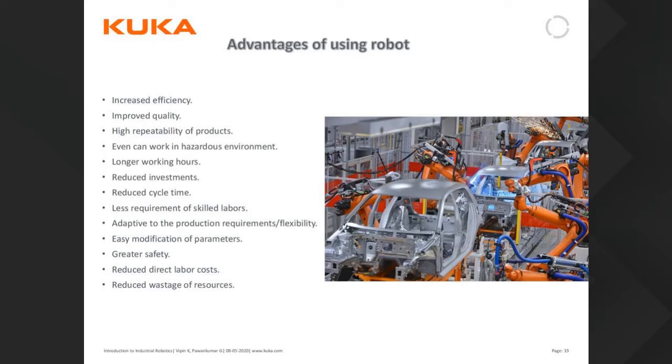Like you are doing a welding and there is some current or some voltage mentioned on that, but the quality is not enough. You need to increase the welding parameter with one small step. However many robots there are, you can increase the parameter in all those robots with some small steps.